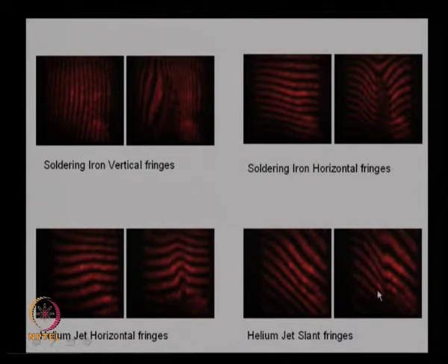The same helium jet now we are doing with cross slant fringes. Depending on what you want to show in your images, you can choose the fringe settings. If you choose slant, you can now see that I have realigned it, now it is going down as density decreases. You are seeing that it is from here, go down and then come back to the original line and go out, which means this line is my jet boundary here, and this line is the jet boundary here, and this region is your metal block from which the helium is coming out. Okay.